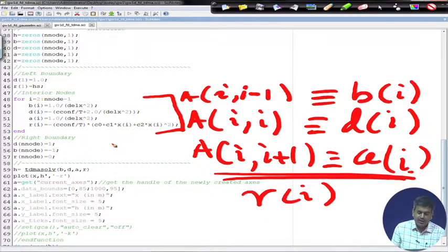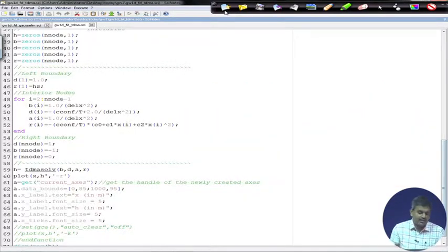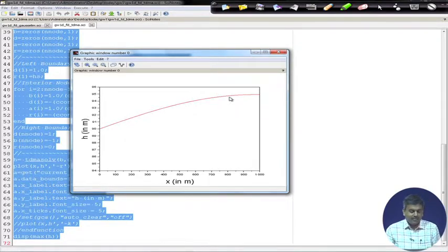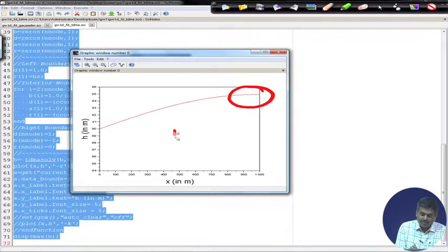What will be the case for right hand boundary with first order, let us say first order boundary condition. We have seen that with other boundary conditions also we can solve this problem. So, let us test this banded matrix structure with first order accuracy. If I run this, again we are getting some solution, and if we increase the number of nodes n, then we can see there will be difference, because in the case where there will be a full matrix structure, obviously the running time will be more compared to TDMA structure.